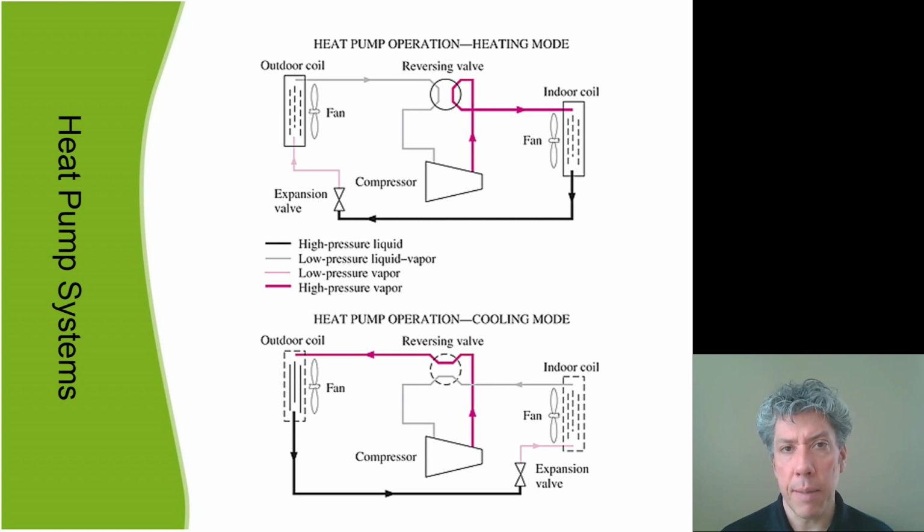So for a heat pump, the cost versus a regular air conditioner is more complicated controls, the reversing valve, but also typically an extra expansion valve. In my system, for example, there's an expansion valve built in with the coil in the outdoor coil, and one built in the indoor air handler unit with the coil in that unit. So there are two thermostatic expansion valves.